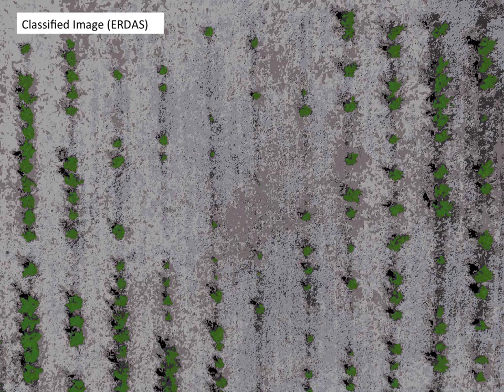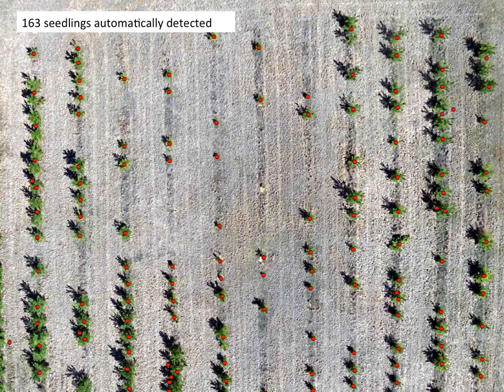seedling in the image. From there, we can run it through some image classification and pick out what's a tree and what's not a tree, right? And so the green areas is what we classified as a tree. And then what we do is we basically get rid of everything that's not green and just take those tree classification pixels and then find the centroid of each individual group and then place an XYZ point on top of each one of those centroids.